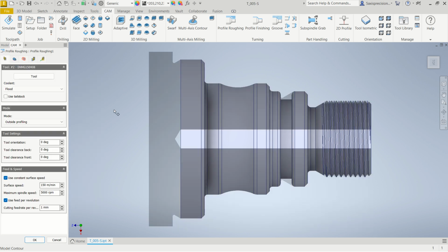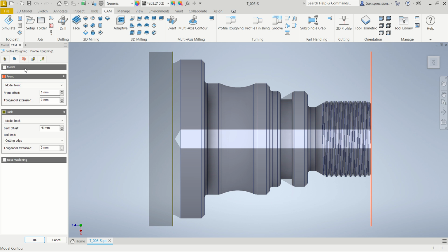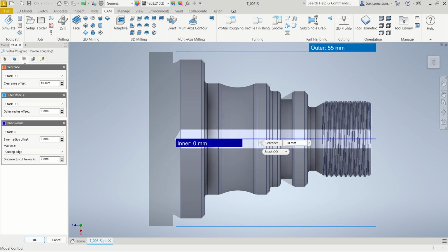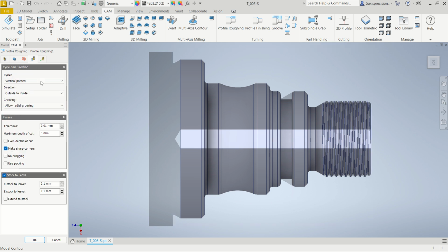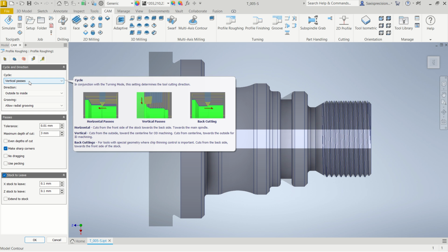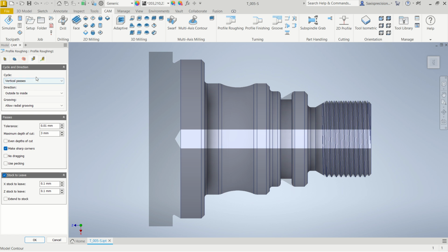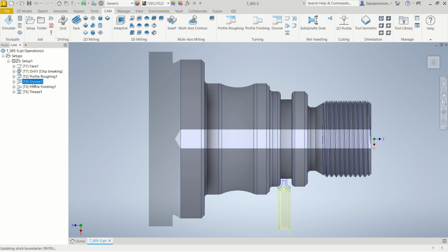What I'm doing is I'm not doing what we call turning along Z. I'm turning along X. I'm using what we call vertical turning. Vertical turning along X. So you feed along X as you turn, not along Z. We call it face turning. I'm using face turning. I like face turning. Okay. And then from there I do a groove.